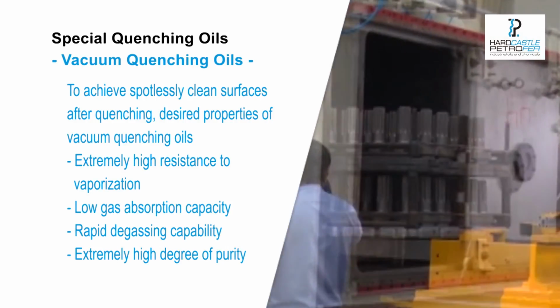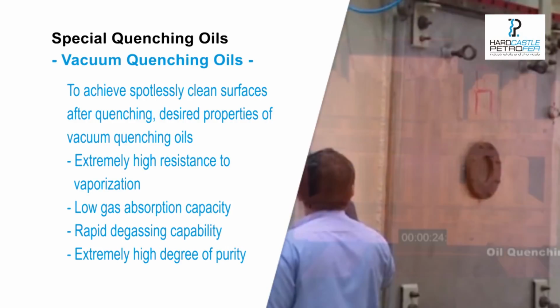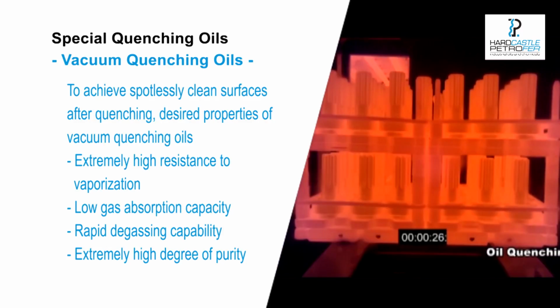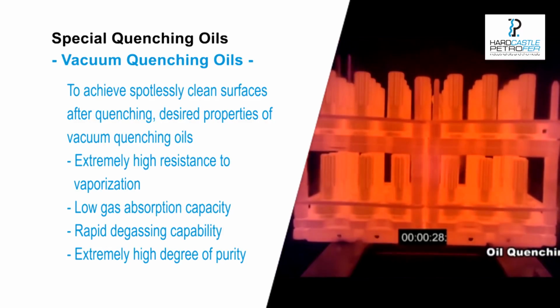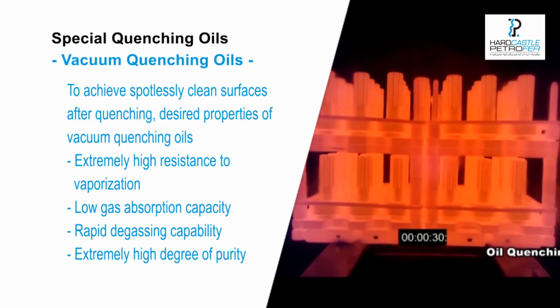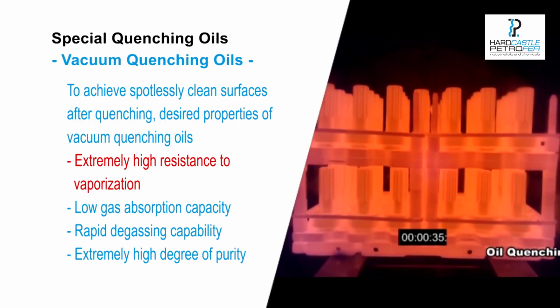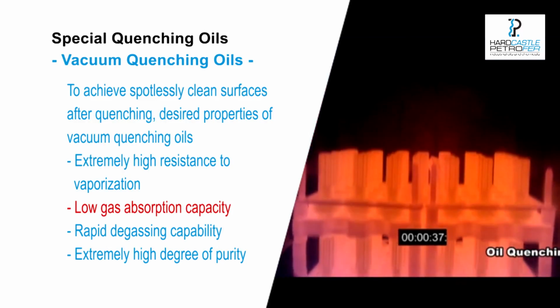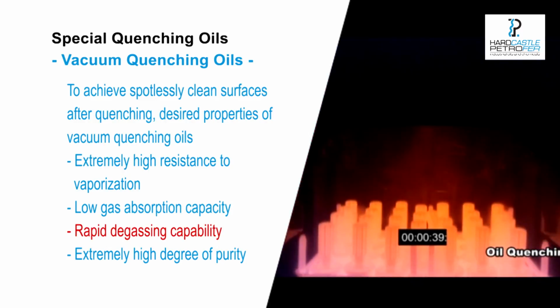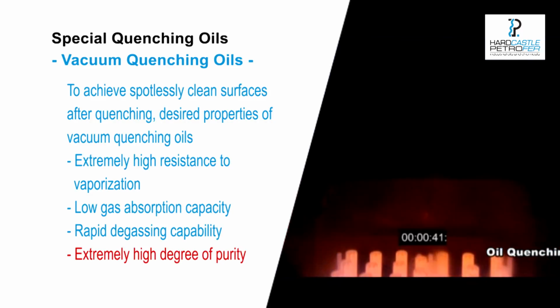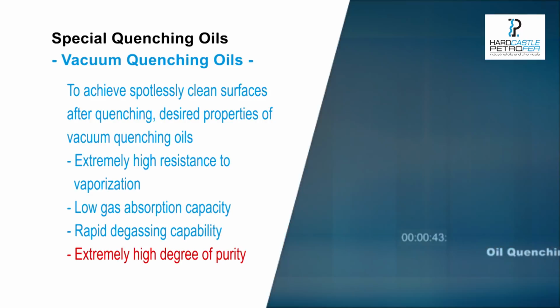Hardcastle Petrofer also has an established range of vacuum quenching oils which have been developed with the following special properties in order to achieve spotlessly clean surfaces. They offer extremely high resistance to vaporization, low gas absorption capacity, rapid degassing capability, and an extremely high degree of purity.